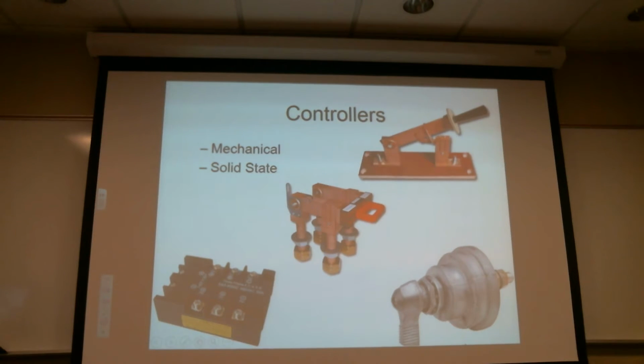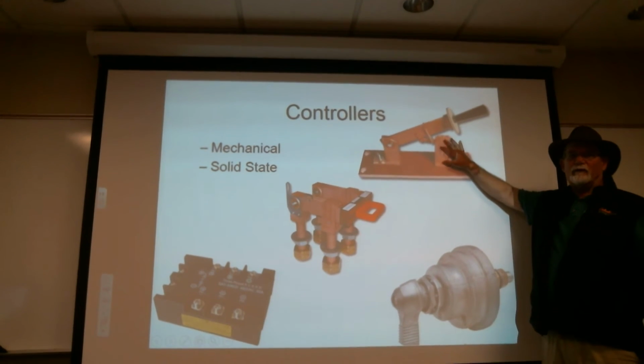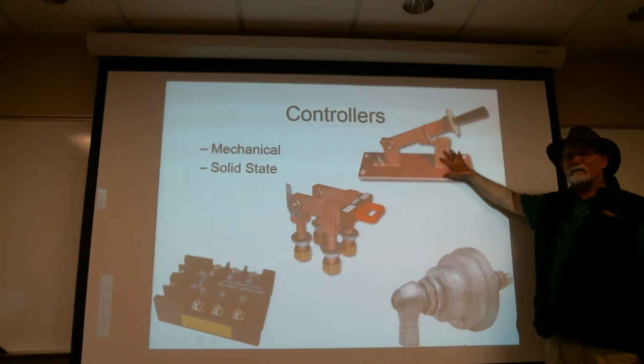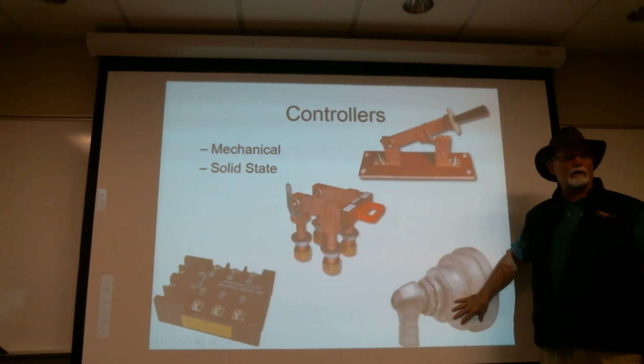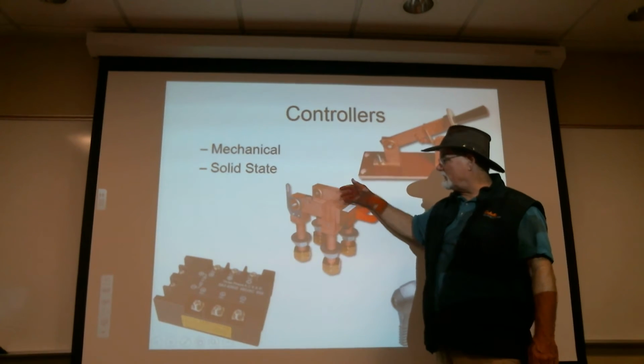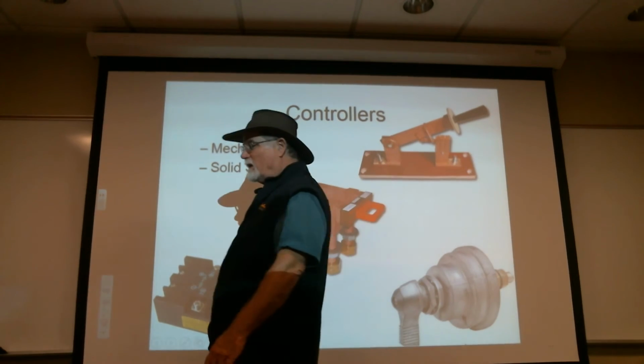Some do an open-close per actuation. They can be very, very high current, like the big knife switches. They can be sort of medium current. The distinction between this one and this one is they may both handle the same amount of current, but this one, if there are gaseous fumes around, could make your day shorter than you planned, whereas this one hopefully is sealed, so the spark that occurs isn't going to light anything. This one here, look at the 3 different blades. There's a whole bunch of surface area. This thing is designed to handle some current.